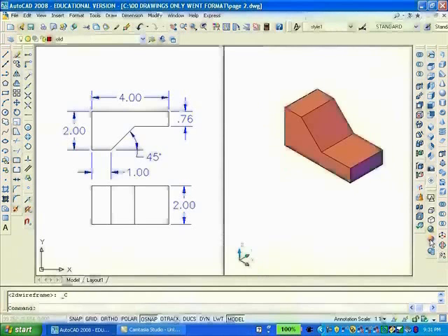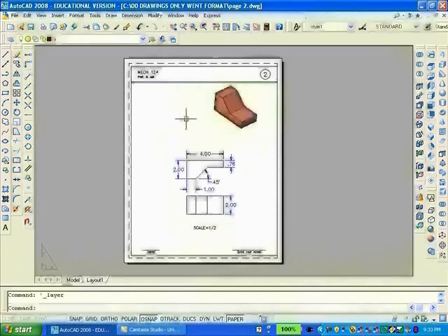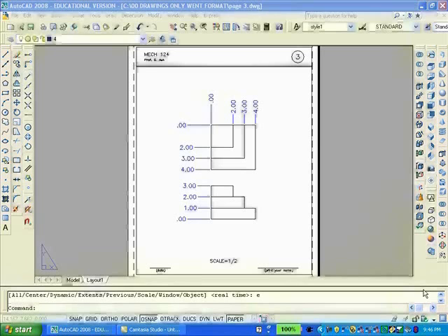After rendering, the solid is complete, and I can click on the Layout 1 button, move into paper space, and create a small rectangular viewport for the new solid. This drawing consists of 3 solids which have not been joined together.